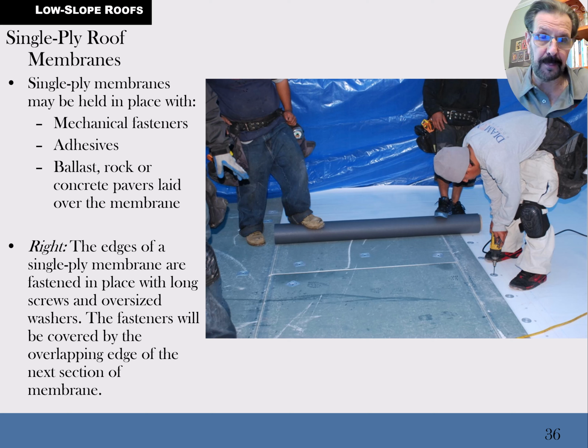You need to start at the bottom, and as you work higher, that's what we're looking at. The lower roof would be on the right-hand side of the page. Here on the left-hand side, we're at a slightly higher elevation. It's not that you can really tell, other than the fact that we have to lap them the same way we do shingles, so that the water will roll off of one sheet and onto the next sheet. So if there are any flaws in the seam, you're still managing to keep the water rolling from sheet to sheet down the roof. So they're putting fasteners down first.